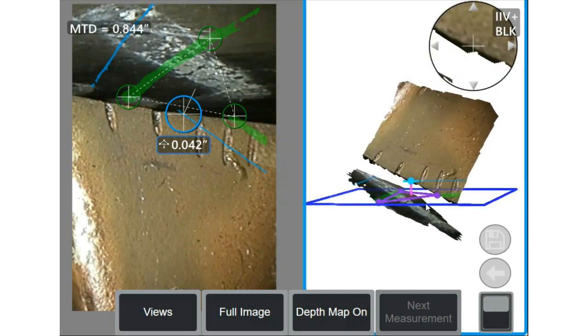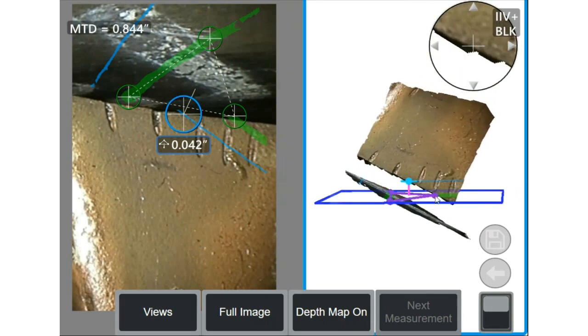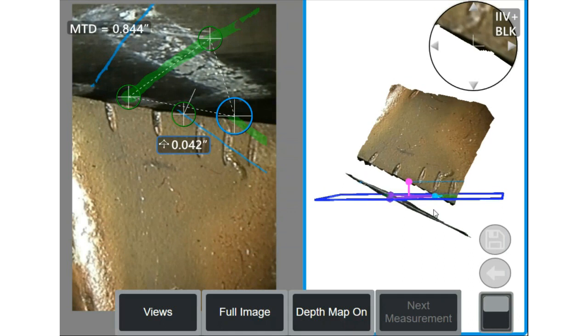And all of a sudden, you now start to realize that this point, which is this point, and if you noticed, I clicked on that point in the point cloud. I can now move these points in the Real3D point cloud, and you notice that your reference plane is tilted to the shroud material, and it just completely is not the measurement you want. Is it really 42 thousandths?